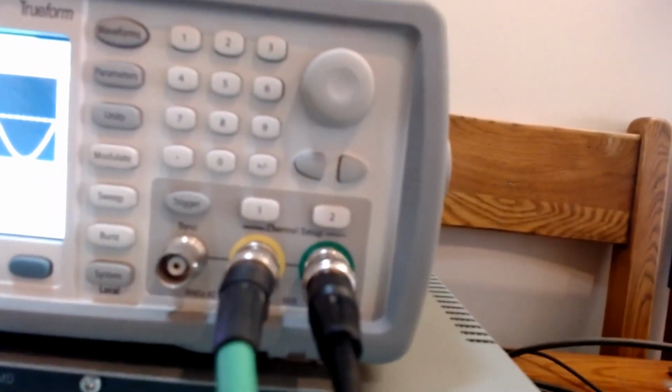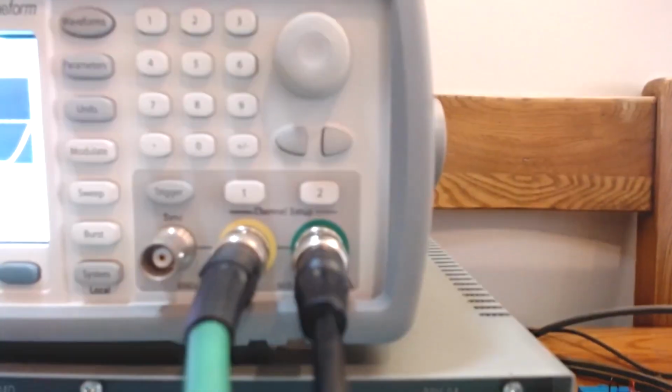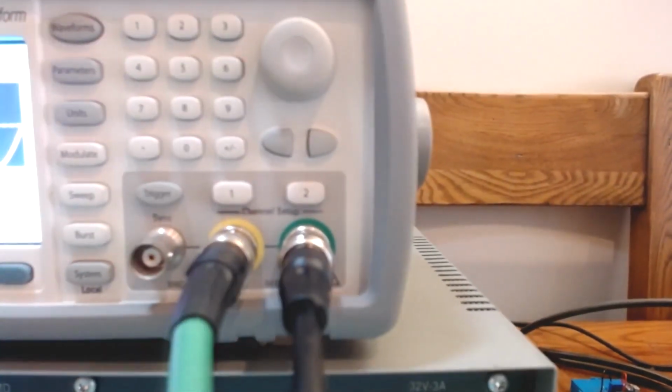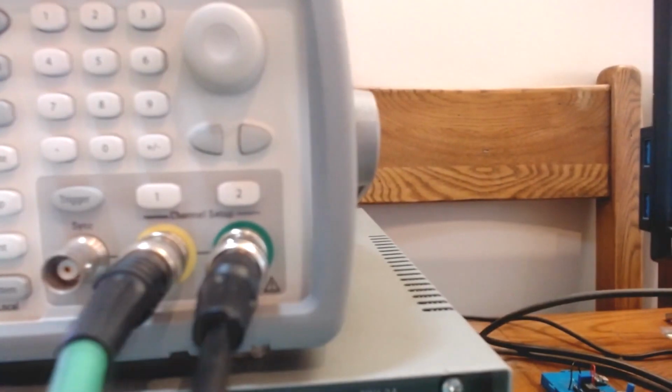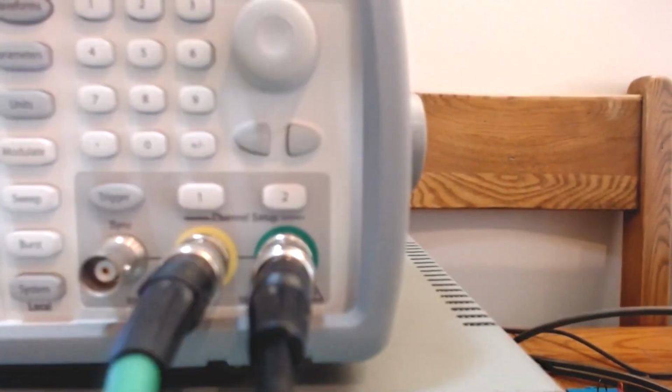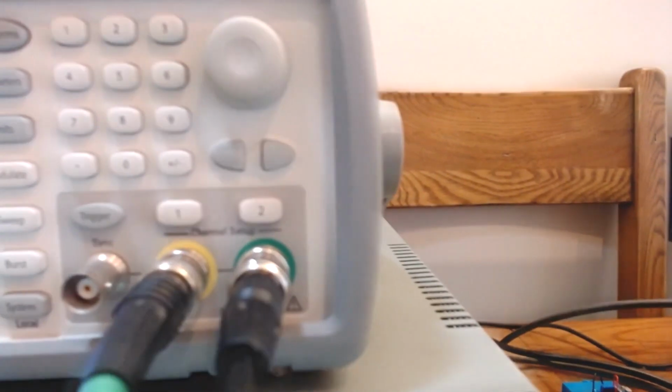So here you'll see a signal generator, and I've got two channels connected to it, channel A and channel B. On channel A, I've got a sinusoid of 1 kilohertz, 1 volt peak to peak. And on the second channel, let me just read off what I've got. I've got a 1 megahertz, 5 volt digital logic signal, 0 to 5 volts, and it's got an offset of 2.5 volts, which is really useful to demonstrate certain things to you.